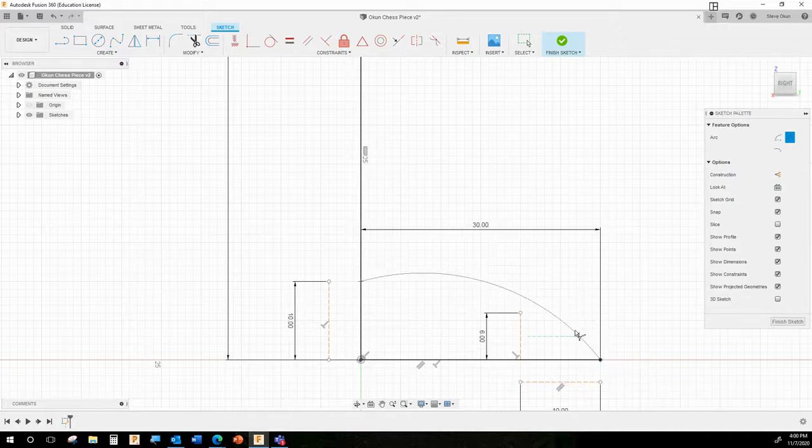And then if you notice, as I drag my mouse away from the endpoint, once it's got 2 endpoints, it starts making the arc. And now it's waiting for me to place a point on the arc. And when I place that point, it will finish drawing the arc. So I have been told when the arc is 10 millimeters away from the edge of the base, it should be 6 millimeters high. So that's where I'm going to place the 3rd point, and that makes an arc.